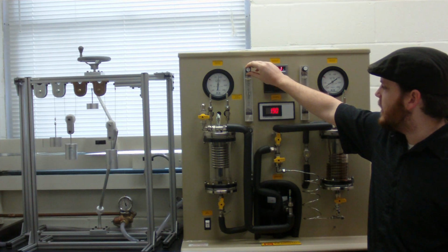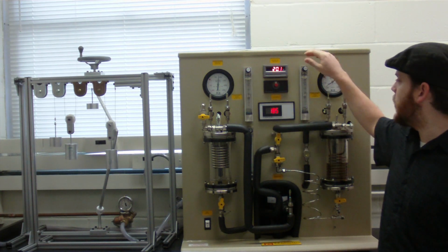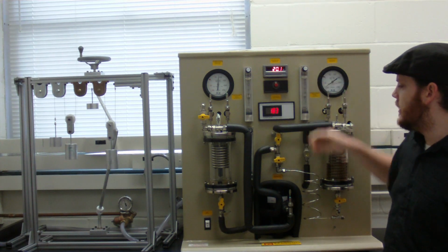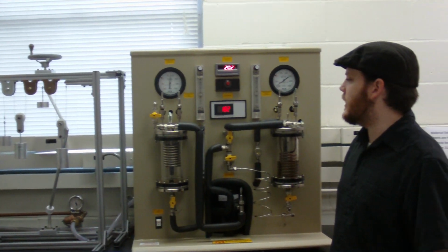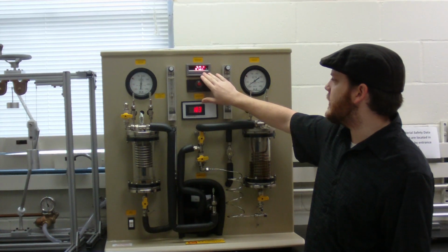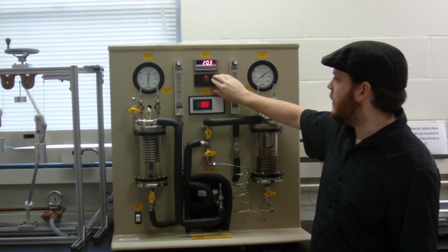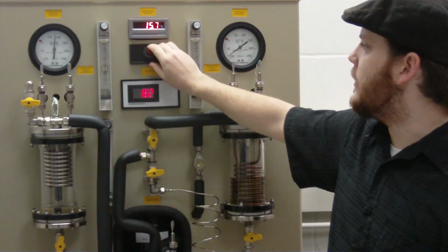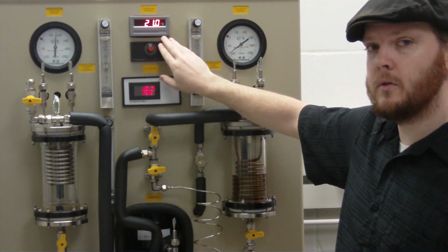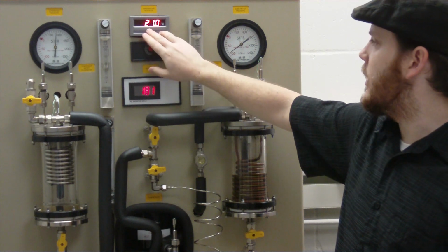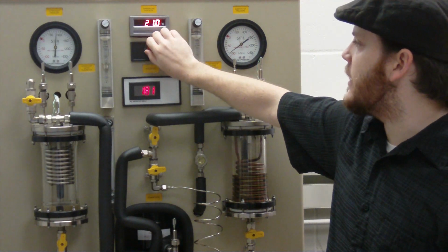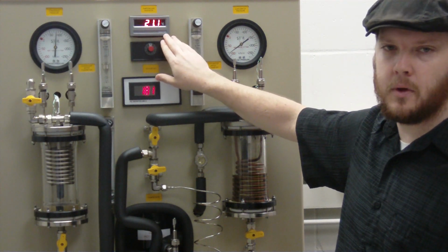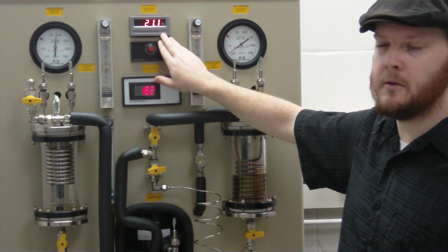You're going to adjust these twice to get the values you need and let it reach steady state. You'll see the temperature readout for all 8 sensors by turning this dial. Make sure you give it a few seconds between turning and that the temperature has steadied out. That's how you'll know it's reading the correct thermometer and that you're at a steady state.